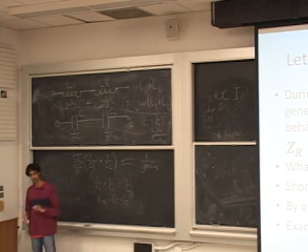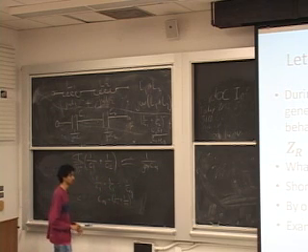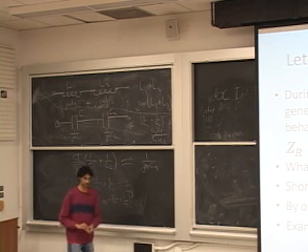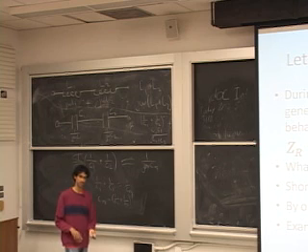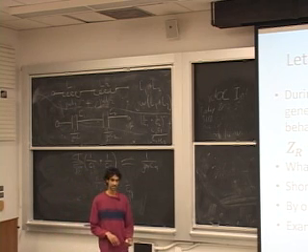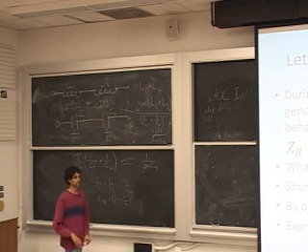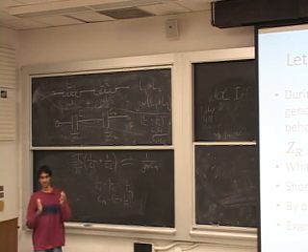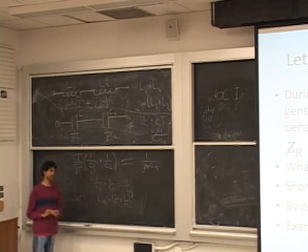So this is why impedances can just add like normal resistors, because we've already accounted for the way that capacitors and inductors add. That's why we have j omega L for an inductor, so they add together in series. And why it's 1 over j omega C for capacitors, because capacitors add in that inverted manner. The reason why goes back to how a capacitor is constructed. That was part of Monday's talk about the areas adding together versus the separation between the plates adding together. So you can refer to that about why this is the case.